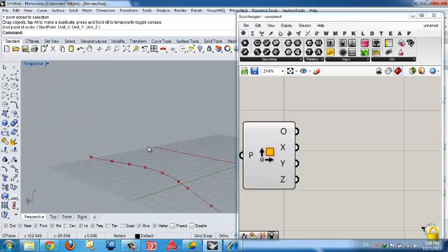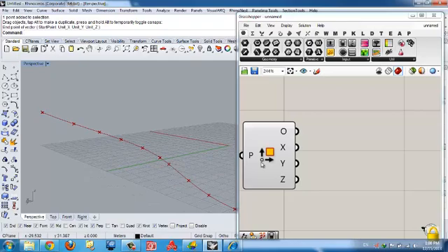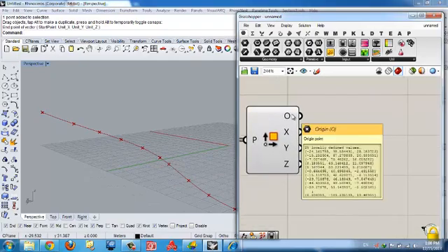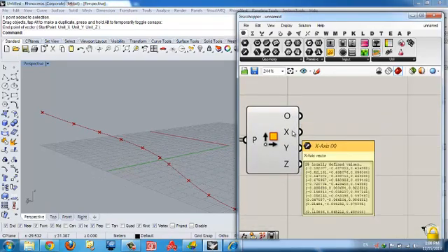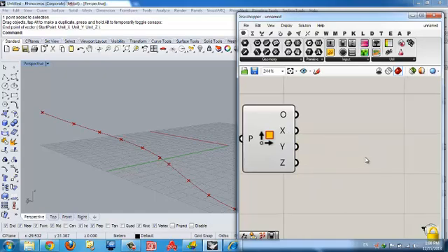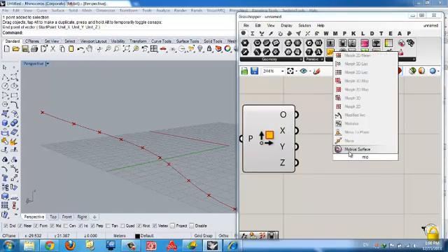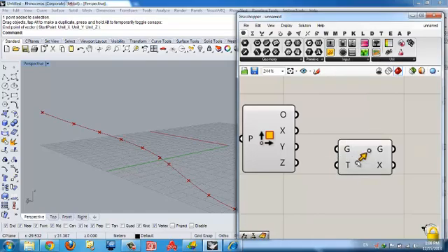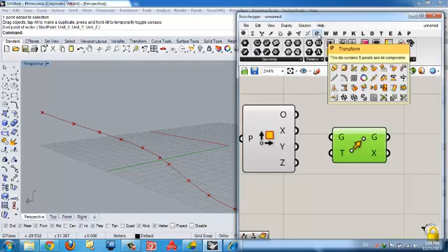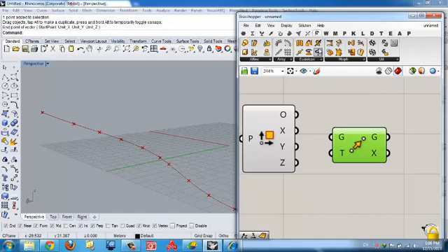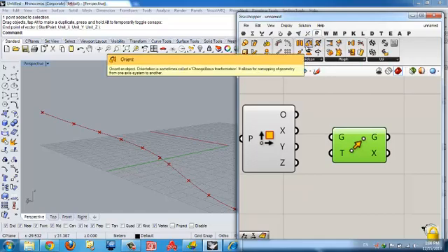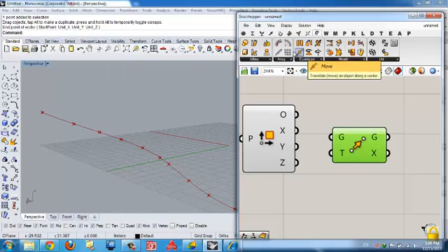I go for the X, and what I do is move them around the x-axis with a pattern. What I want to do is move this point around the x-axis. So we just double click on Move. You can see it has it here. You have all of them in the transformation tab: rotation, orientation, mirror, move, arrays, scaling, and projecting.